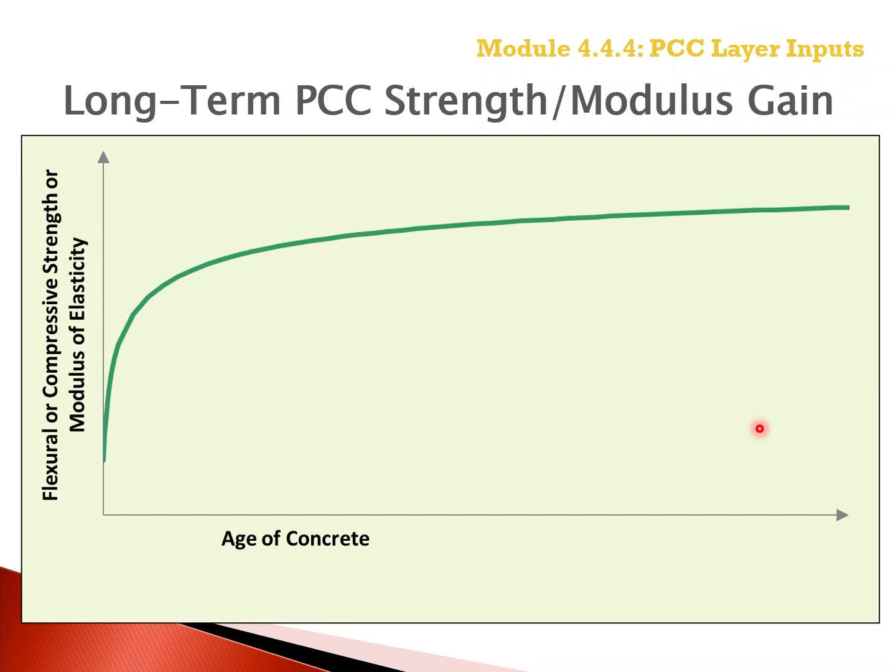The growth function embedded in the PMED software considers the curling method, the loading method, and the cement type used in the concrete mixture. All of those do have an impact on the growth function. And also the growth function is identified in the MEPDG manual of practice.